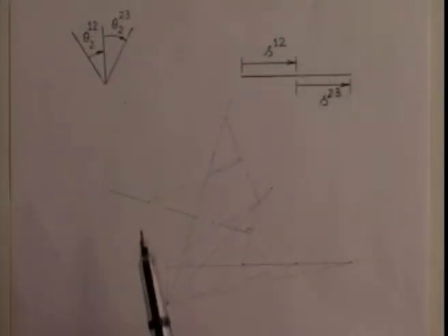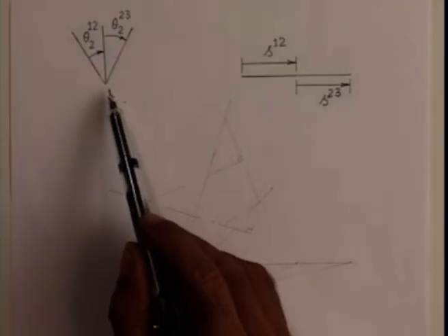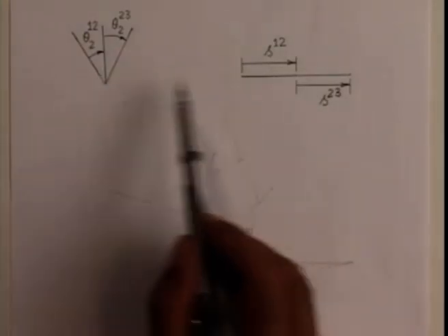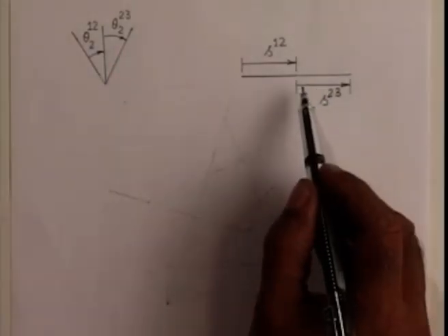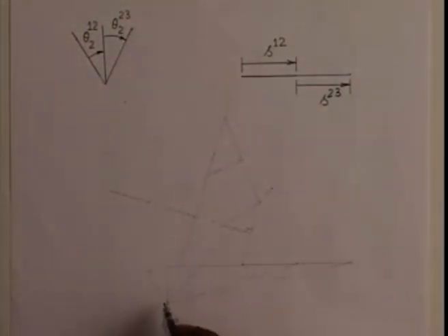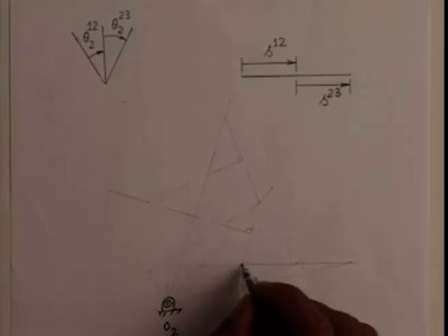Let me now say this design of the slider crank mechanism to generate these 2 pairs of coordinated movements as we have seen in the previous problem. It is the same problem, only thing we solve it a little differently by assuming the crank pin location arbitrarily, say here, which we call O2, and we assume the other moving hinge which is connecting to the slider at the first position is here, which I call B1.